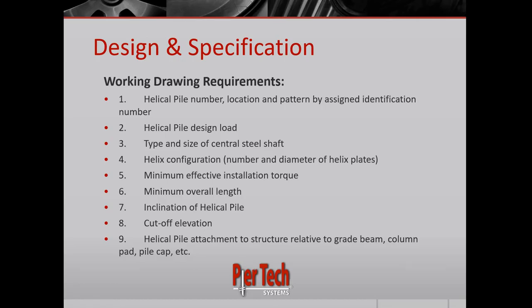One other thing I didn't put on here was the tolerance. That's also going to be specified on the drawings. How far off of location can you be? It's very important to have an understanding of that before you go do the project, or else you could get installing a bunch of piles and have to go back and relocate and move some of those. So make sure you really plan this out before you start your project.